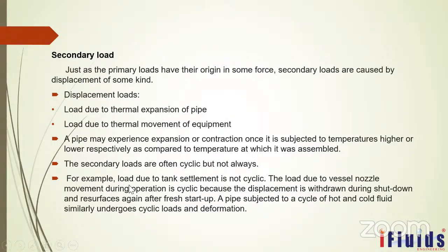For example, secondary loads may be cyclic, also not cyclic. For example, a load due to tank settlement is not cyclic. Whenever you construct a new tank and you are connecting your pump discharge to that tank, the first time you commission the tank, whenever you start to fill the tank, the tank may get settled. That means it settles on the foundation. That is not a cyclic load. Once it happens, after that there will not be any changes in the tank settlement. Those kinds of load are called not cyclic.